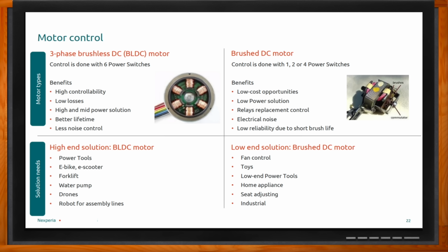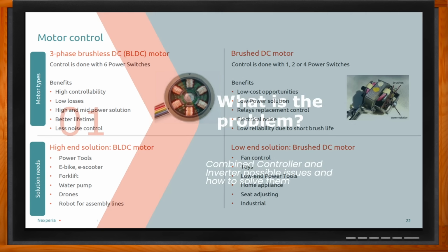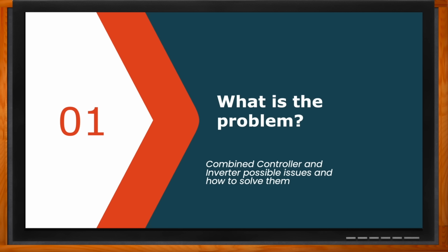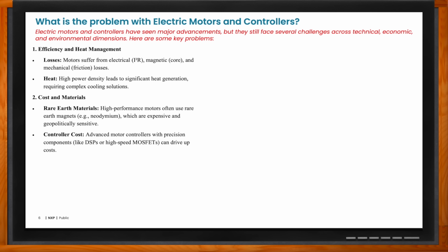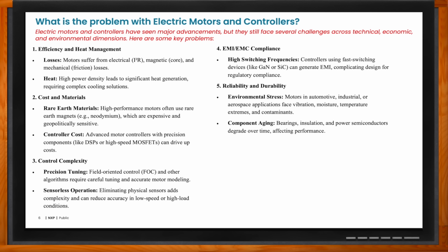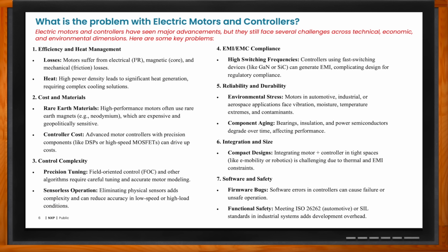So, Art, what do you think are the biggest challenges specifically with electric motors and controllers these days? The challenge is selecting the proper power amplifier to drive them and mating that with a proper MCU or DSP controller, which is digital, and being able to control that motor in just about every application that we can imagine. And there's a multitude of applications where BLDC motors are used, from something small, let's say a small drone, versus something that lifts big, like I said, papers, or just about anywhere in the warehouse industry. Also somewhere in between, where you have assembly type robots in the automotive or any other assembly world.